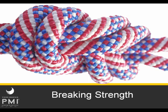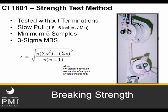Life safety rope standards measure breaking strength and diameter and pretty much everything else as being very, very accurate. The breaking strength of certain commodity ropes and of the old Federal Test Method 191 was more oriented on what they called a nominal strength. A nominal strength was focused on the diameter. It measured the diameter of the rope, and it weighed the rope, and it assumed that a rope of a certain diameter and a certain weight would be a certain strength. We don't do that in the life safety rope standards. We tend to measure more specifically.